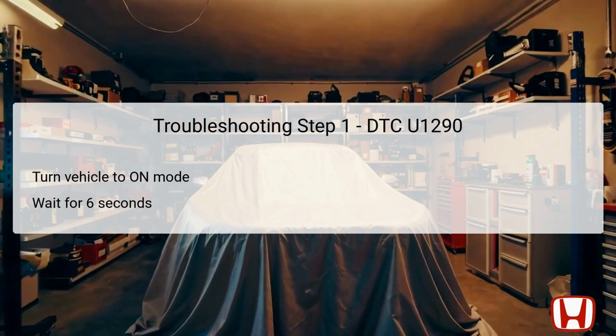It is important to wait for at least 6 seconds after switching to the on position. This waiting period allows the systems to gather necessary data and for communication checks to occur between the different control units. If the fault persists after adhering to this initial step, further investigation into the power and ground circuits will be essential for diagnosing the communication failure accurately.